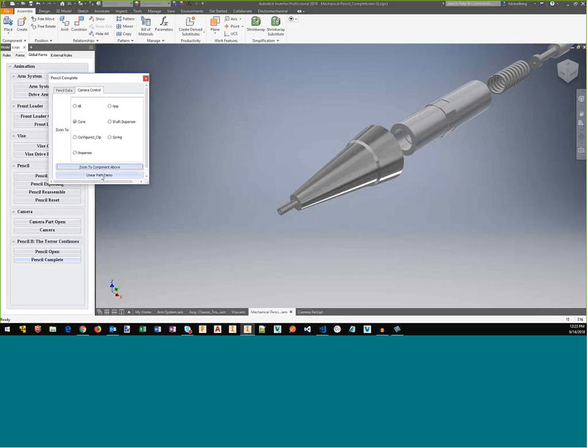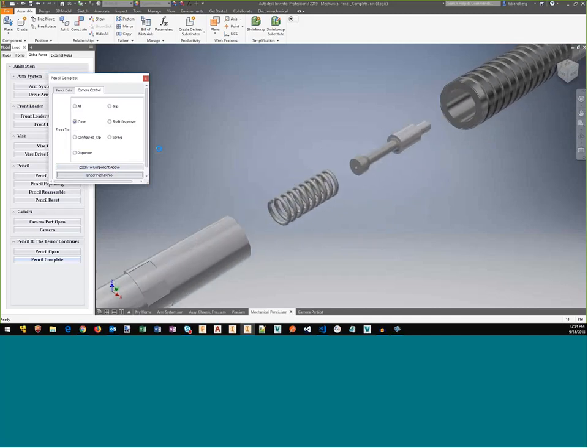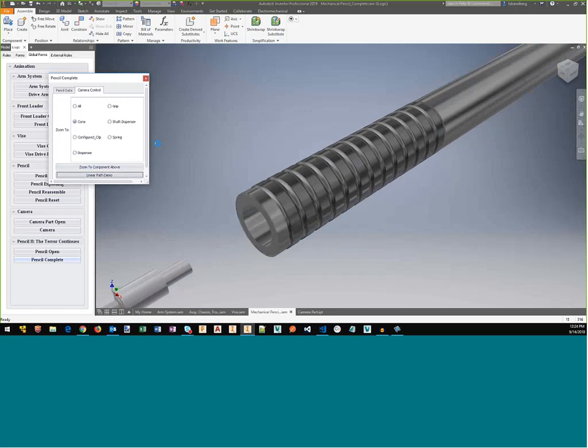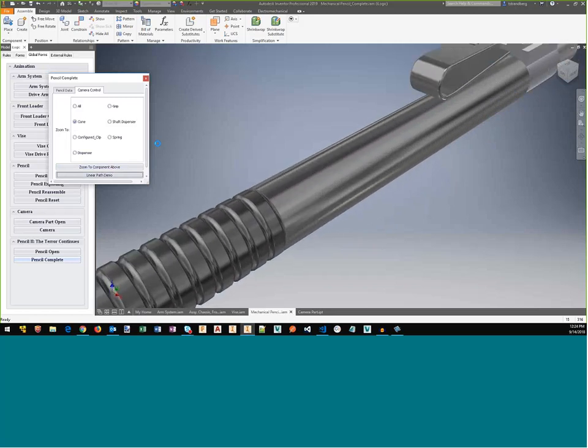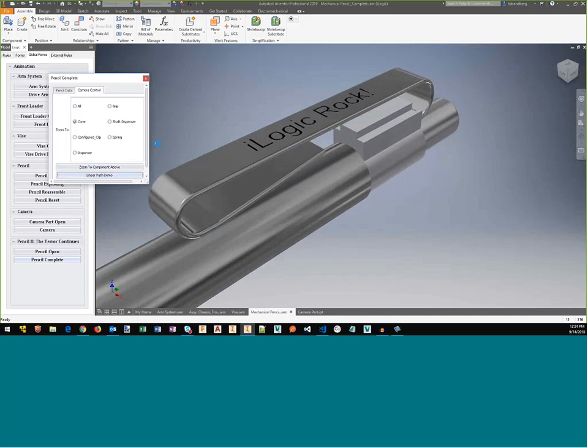We can even drive that camera view along a 3D path. We actually used a 3D sketch to define that path, so this almost gives us that flyby or walkthrough effect. So we could define that. Think of, if you really are thinking outside the box here, you're already trying to decide, okay, how can I define a path that allows me to cruise by the object, change my camera angle at the end so that I swing around the backside and then cruise back up the other side.